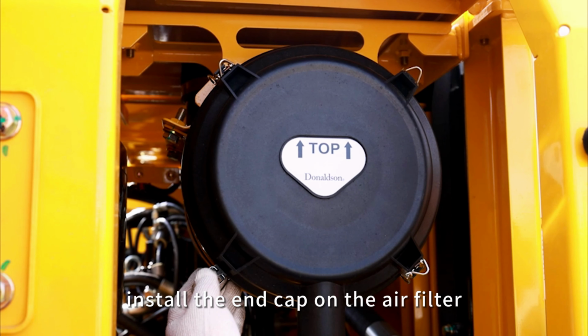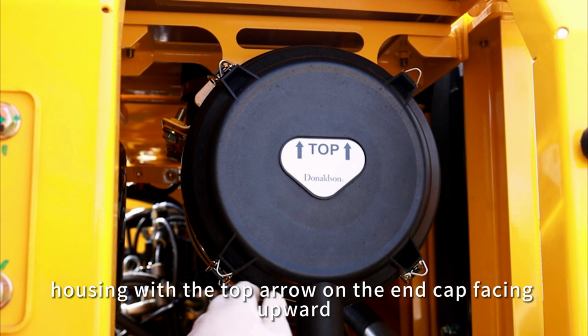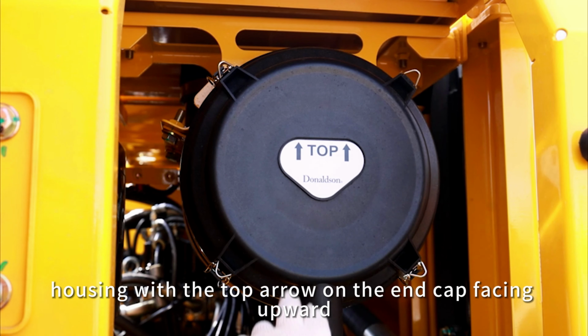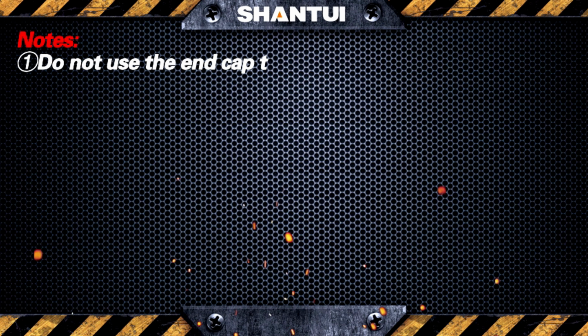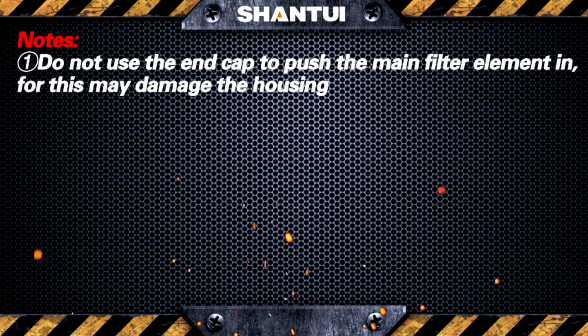Install the end cap on the air filter housing with the top arrow on the end cap facing upward, and fix it with the lock buckle. Notes: 1. Do not use the end cap to push the main filter element in, for this may damage the housing and the lock buckle.